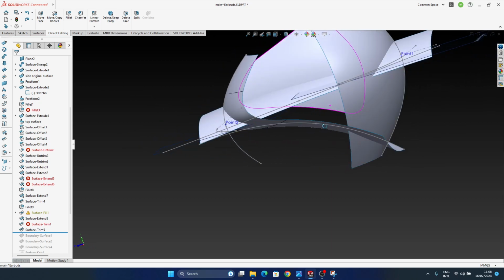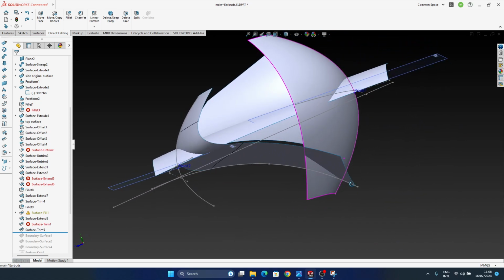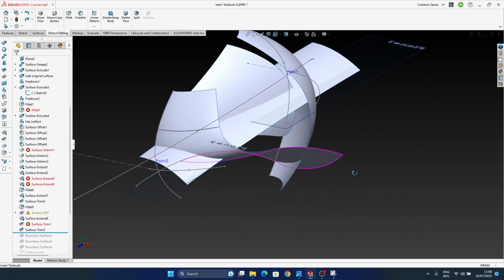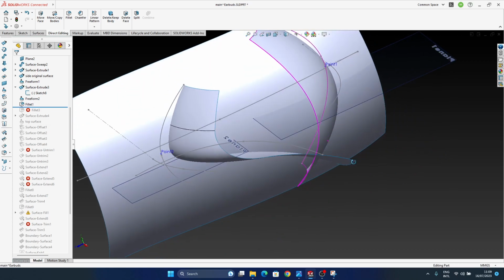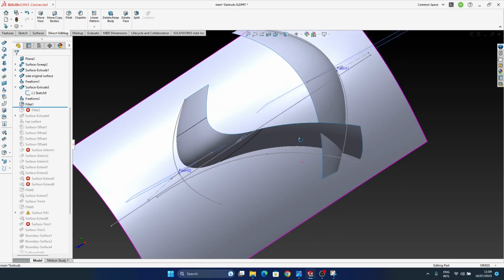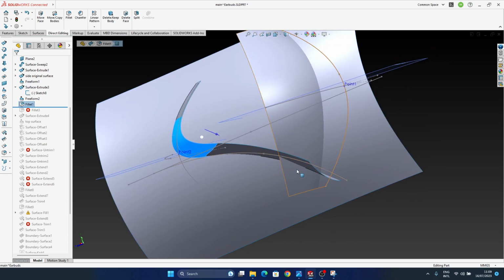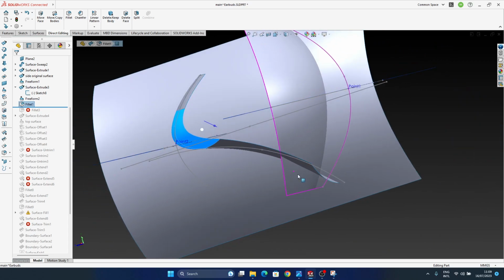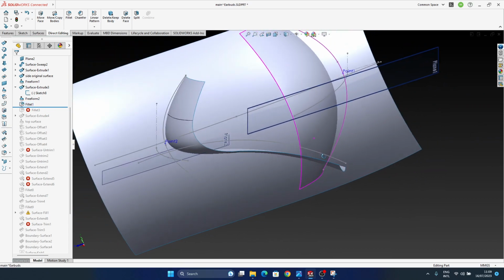Remember when I said in the previous videos that SolidWorks is quite sensitive to building fillets directly using the surfaces. God knows what's the reason behind doing that, but that's how SolidWorks is. So instead of doing that, I am going to join those and do the fillets after I'm trimming the surfaces instead of having fillets directly done with the surfaces.